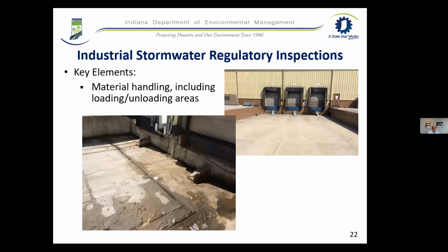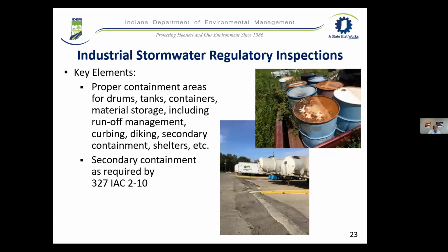Sometimes you can get vehicles going in there that are leaking oil, that type of thing. Can you equip your drains with some kind of absorbent inlet protection to capture or absorb any oils and greases and things that would be washing off of the vehicles or falling off the vehicles?